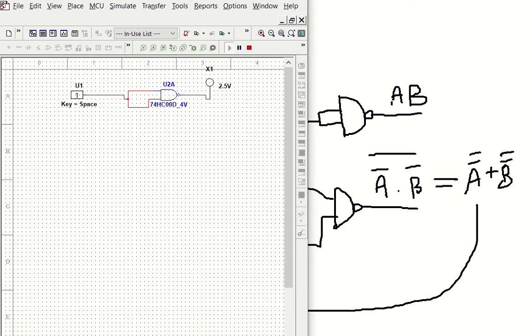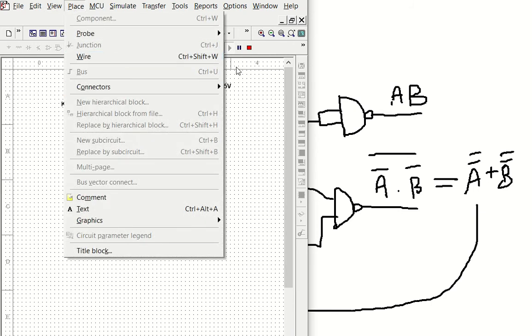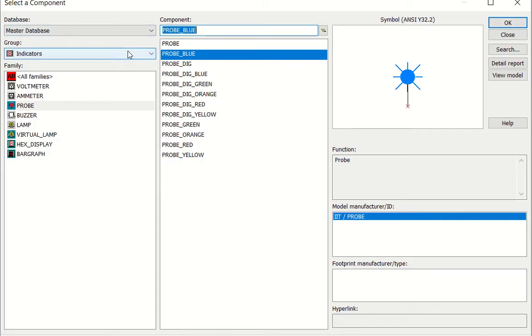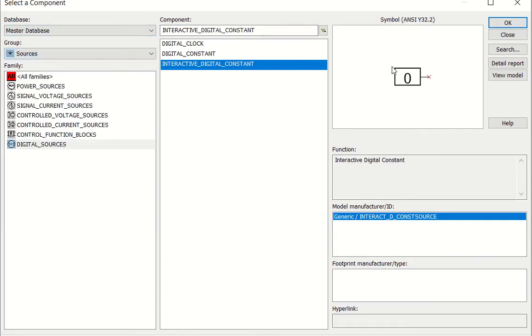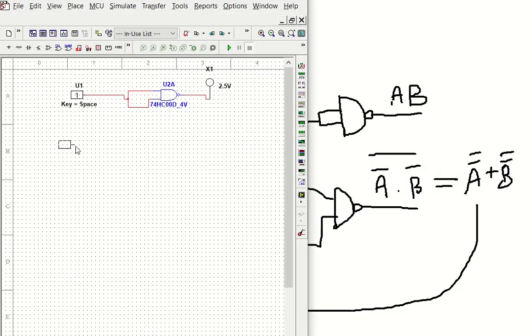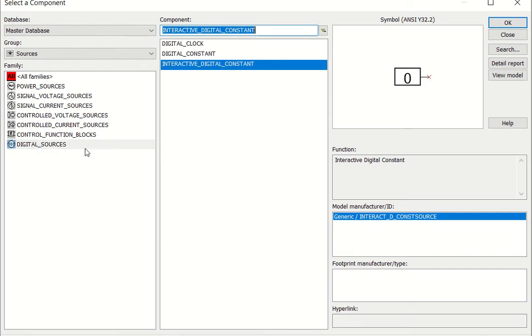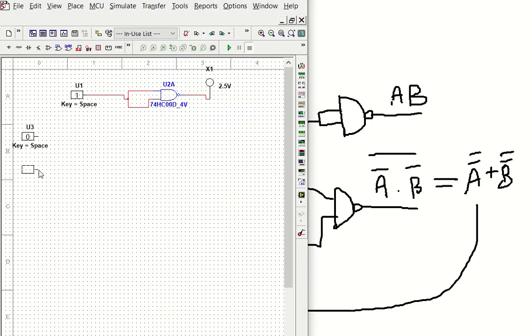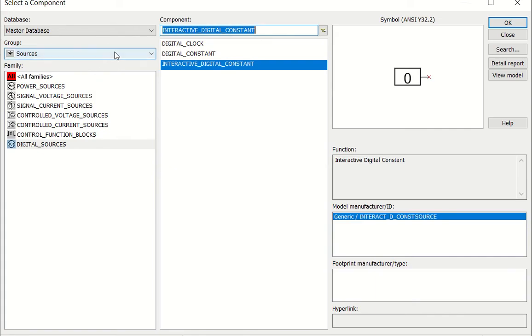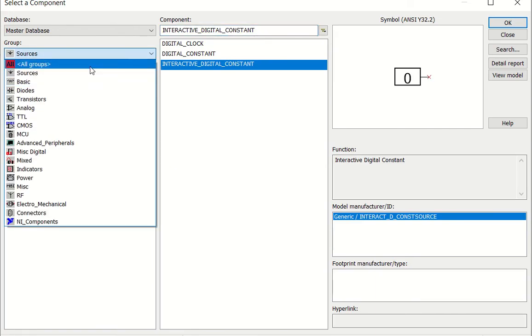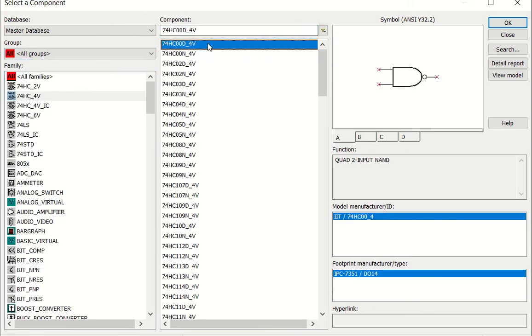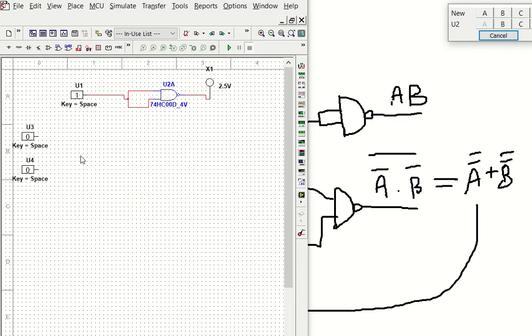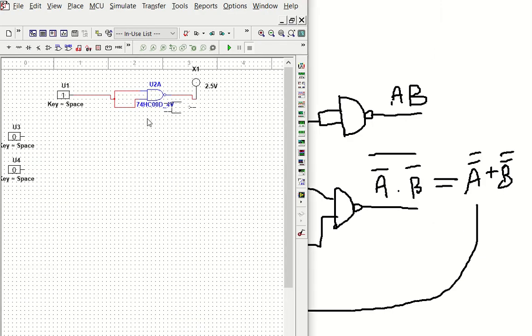So now we can try the next combination, which is the AND gate representation, but using NAND. So we need 2 inputs. Next we need our IC. Okay, NAND IC. We can place it, let's say any series.